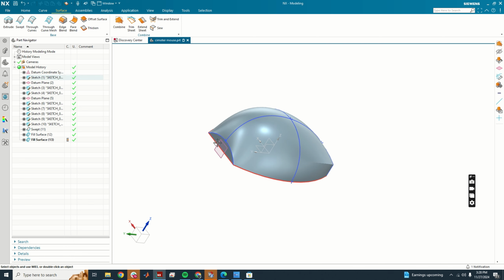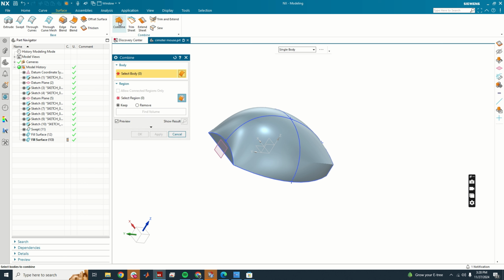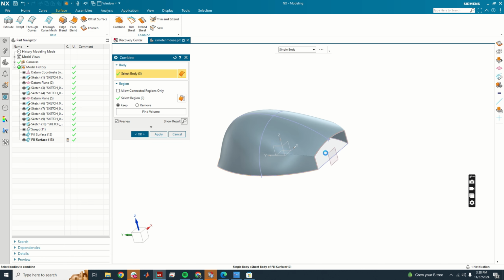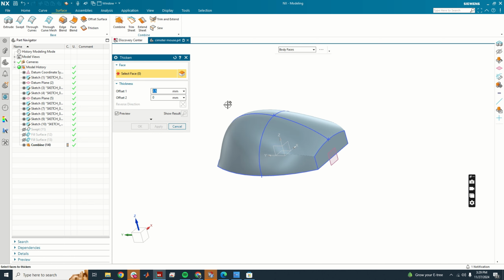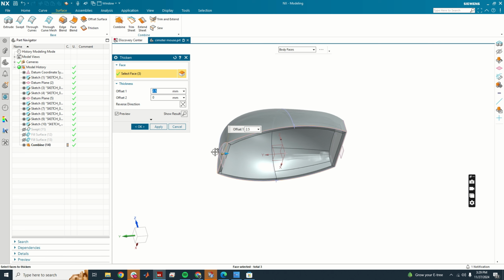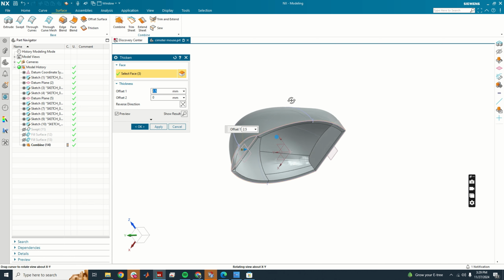In case you want to combine multiple surfaces into one, there's this other tool, combine, routine multiple intersection sheet bodies. So if I click on this, it's adding a couple of different surfaces together. So I can click on that one, and that one, and then press OK. Now all of these are kind of considered one surface. So if I thicken it now, it's automatically going to include both those sides. So that combine tool might be useful in certain other scenarios, basically.